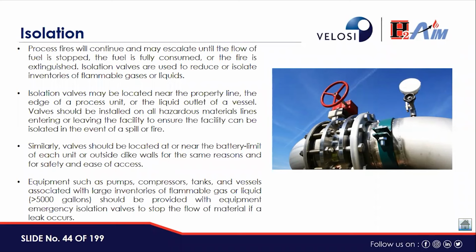Isolation valves are used to reduce or isolate the inventories of flammable gases or liquids. Isolation valves may be located near the property line, the edge of the process unit, or the liquid outlet of the vessel. Valves should be installed on all the hazardous material lines entering or leaving the facility to ensure the facility can be isolated in the event of a spill or fire.